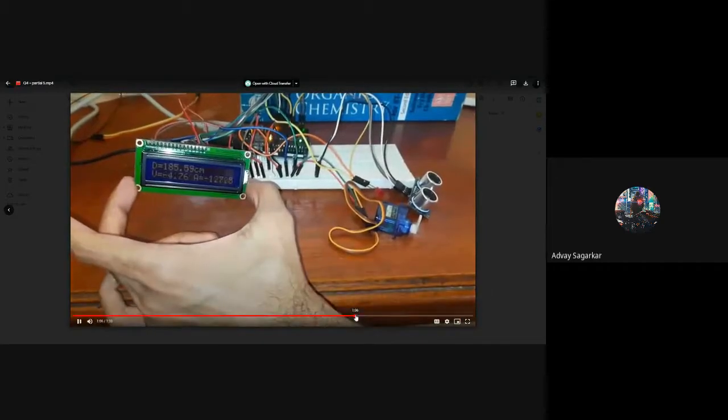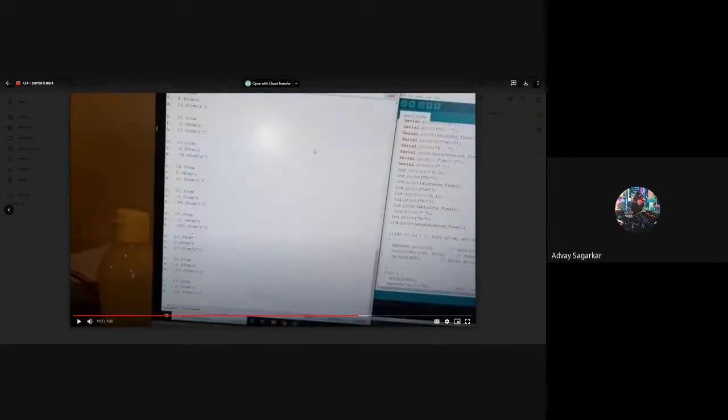One thing that we noticed, in these serial outputs, the acceleration and speed values, especially if you keep the object very constant and don't move it, at least in the implementation that we set up with the code, we were getting a lot of inaccuracies when the object is stationary. The logic we could think of is that the ultrasonic sensor is very slightly inaccurate, so the distance actually changes even when you keep it steady.